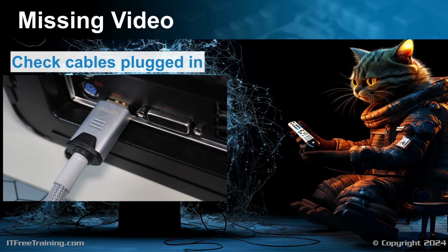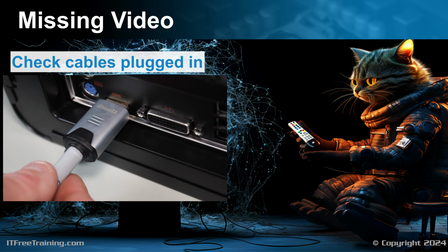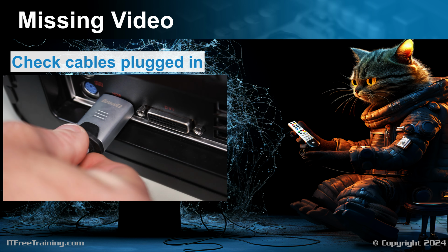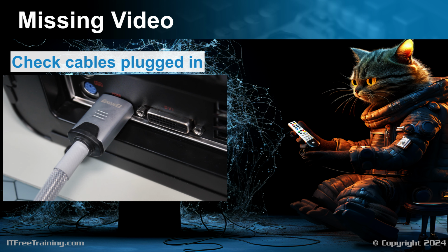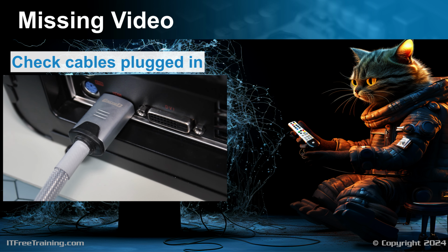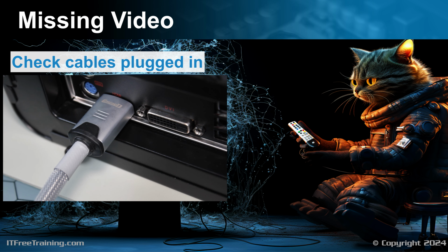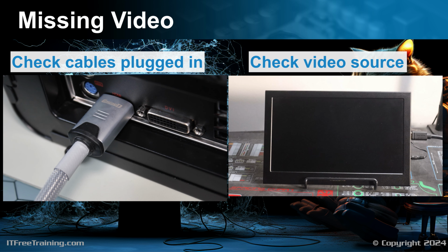Cables can appear to be plugged in, however, even if they are out by a little bit, you won't get a video signal. So the first step is make sure they're plugged in. Just to make sure, I'll often pull the cable out and then plug it back in again, making sure it's all the way in.